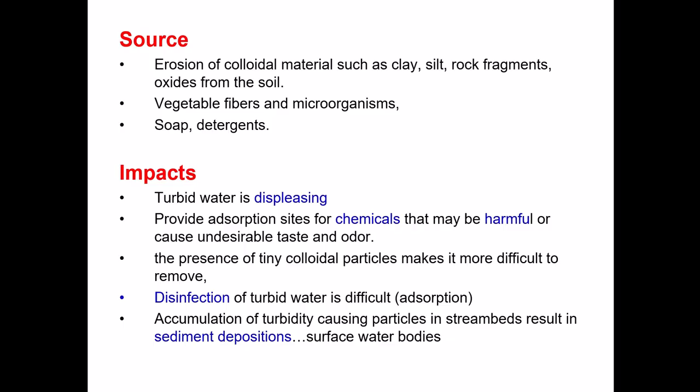This is dangerous because chlorine's main purpose is to kill pathogens, not remove turbidity. When chlorine reacts with organic colloidal particles, it can form harmful or even carcinogenic byproducts. That's why it's important to remove turbidity before disinfection. Finally, turbidity can cause scale and sediment to accumulate in waterways, which can lead to clogging and deposits.